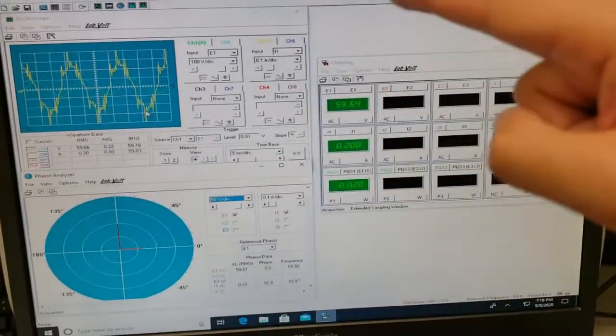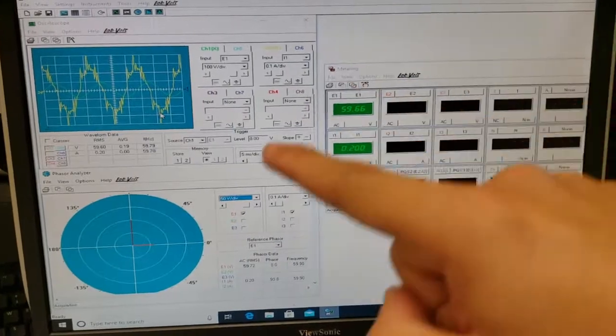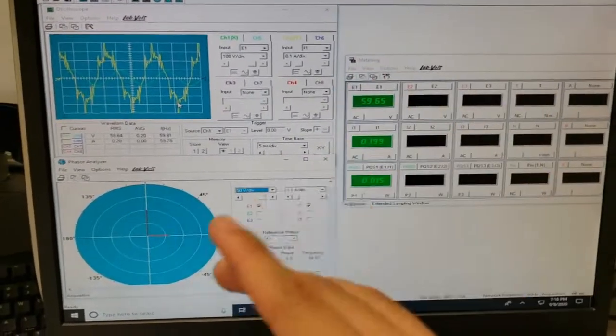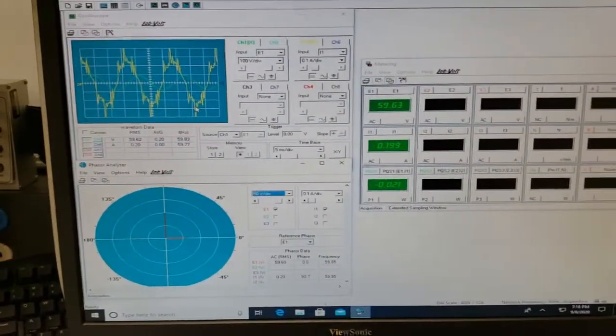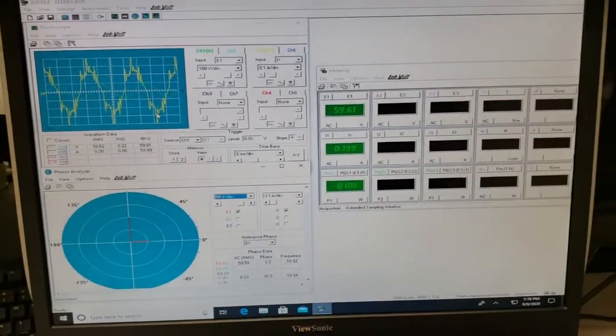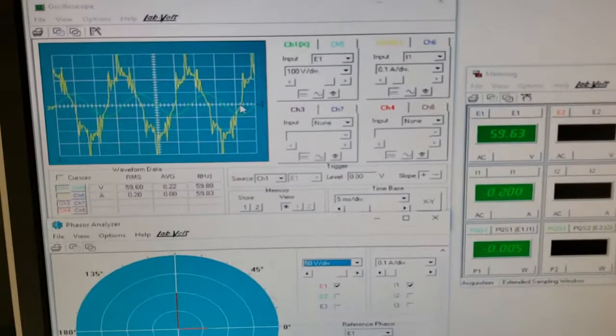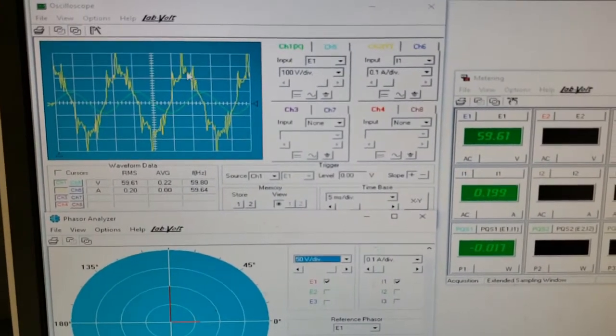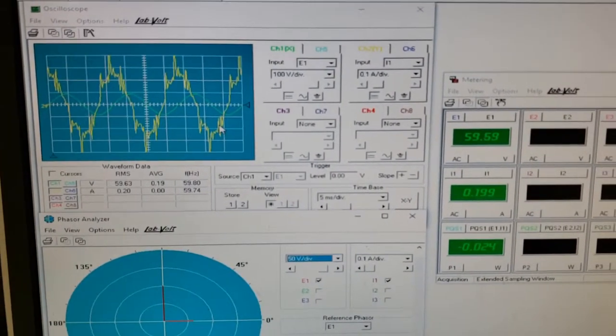So they also have this kind of curve. If you're operating in the linear region, then you'll have a nice sinusoidal waveform. But if you're operating in the saturated region of the hysteresis curve, you'll get these nonlinearities, these added harmonics on top.